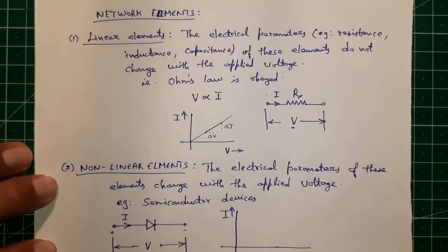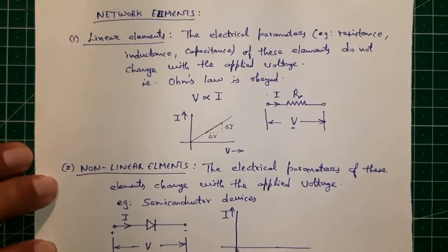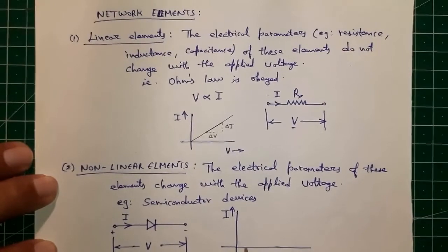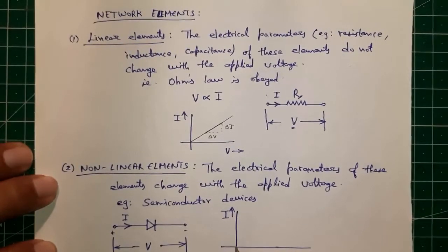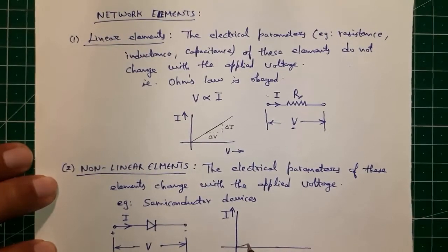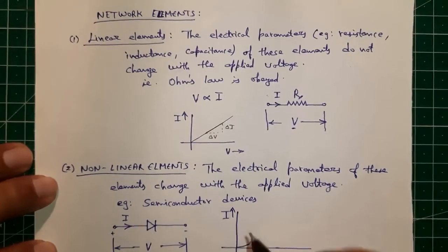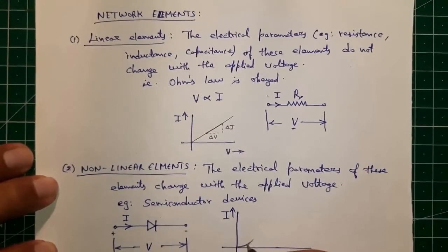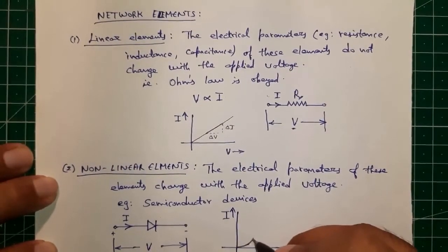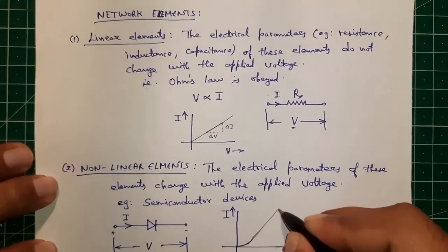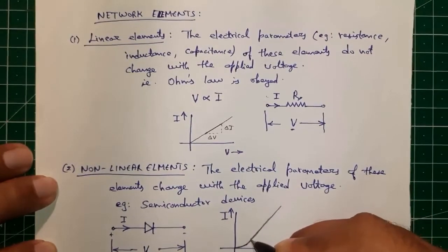We can define, for a semiconductor device, a cut-in voltage or knee voltage at 0.7 volt for silicon and 0.3 volt for germanium, after which we can see that the diode is offering lower resistance than in the non-linear region. Once the diode is on, we get a linear region.